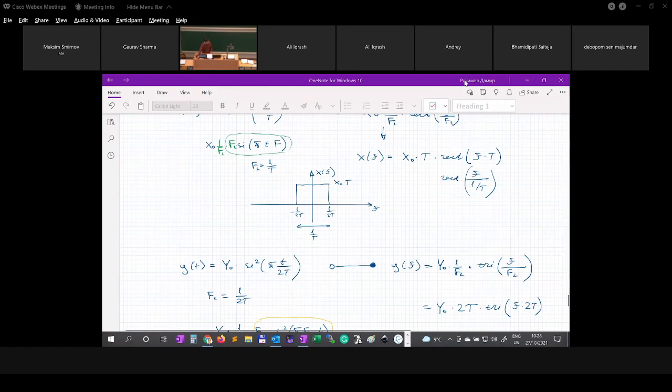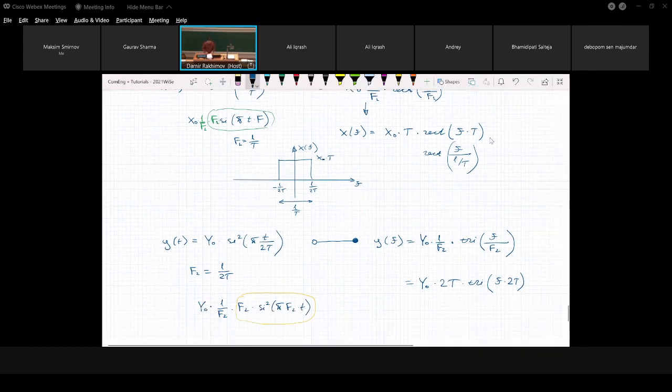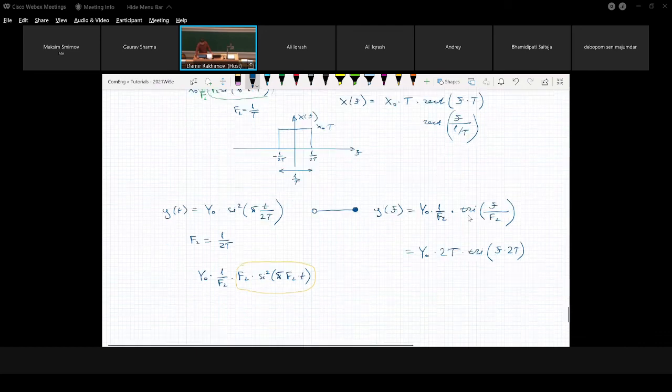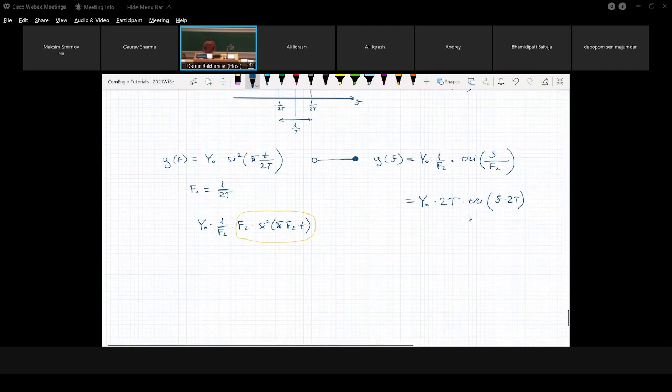No, I mean, there is nothing to repeat. The idea was just that we perform this first shift to intermediate frequency in the digital domain. That's all: we just have a fixed carrier frequency oscillator, but we can choose by ourselves the intermediate frequency, performing this shift in the digital domain. Just multiply numbers and use signal processing to get the signal at different intermediate frequencies. This is just a short discussion.